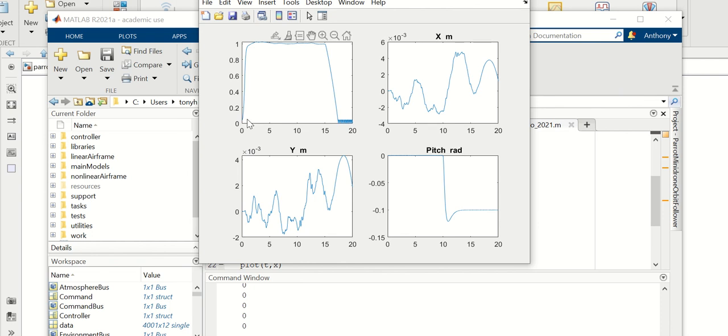And then this is the height change here. And then at 10 seconds, it does a set point change on yaw. And this is the yaw going to 0.1, which is what we put in. So it's not that good. It's got a bit of overshoot and a bit of overshoot there. So you could tune that one to do a better yaw. If you detune this one, it'll probably have a crosstalk on this, and this will get worse.